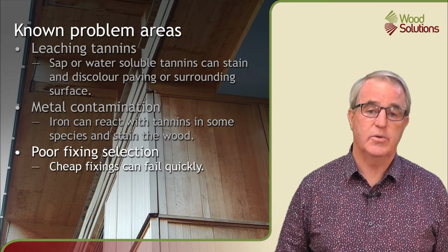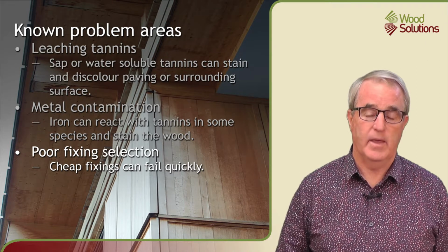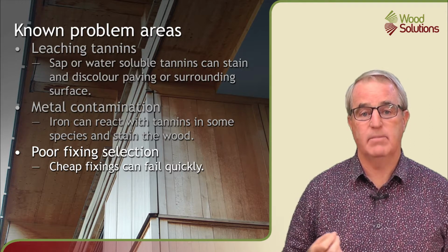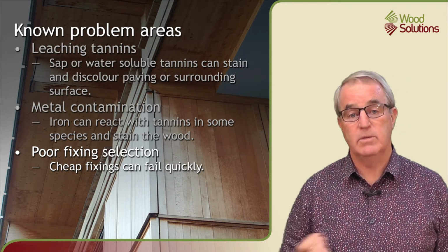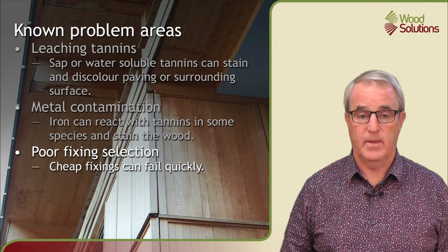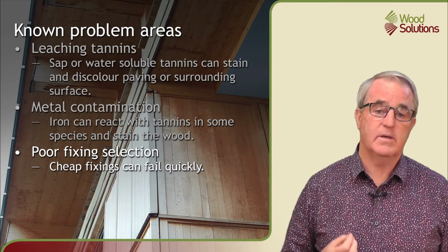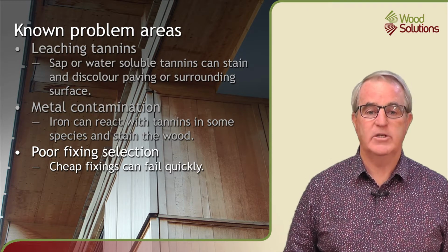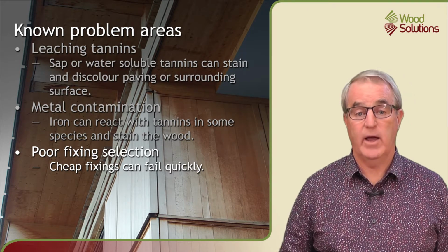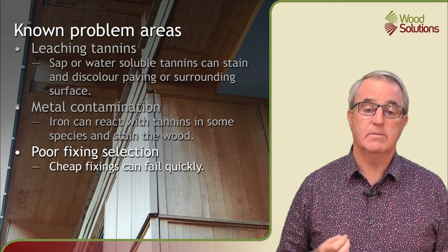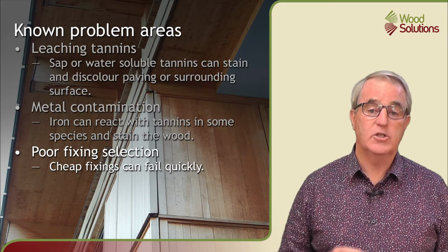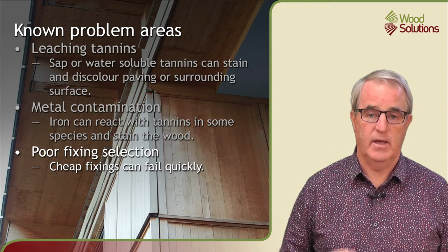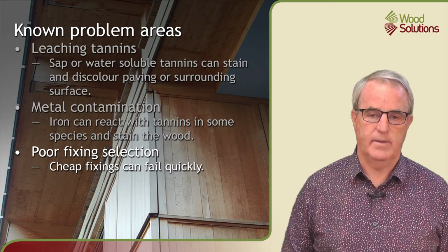The last common issue is poor fixing selection. Timber used outside above ground will only last as long as the fixings and metal components used to join them together remain serviceable. Generally, hot-dipped galvanised material should be suitable. However, if the application is near a beach or an industrial area, higher durability fixings may be required. Internal grade fixings shouldn't be used for an external application. They tend to fail very quickly.